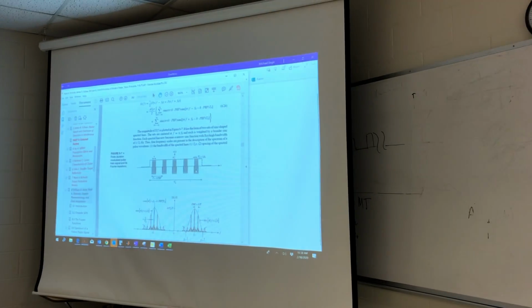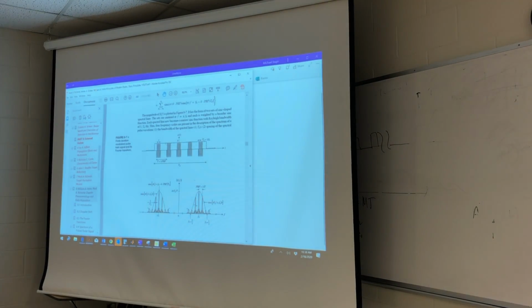So what does this look like in the frequency domain? Well, it'll be centered at plus and minus F0. Then you would have that exact envelope we had back at baseband moved up there. Now you can see that in the frequency domain, continuous time. Once we start sampling and doing discrete time processing, all that is dulled. The sharpness, the crispness gets dulled. And that's where all the really clever signal processing comes in.